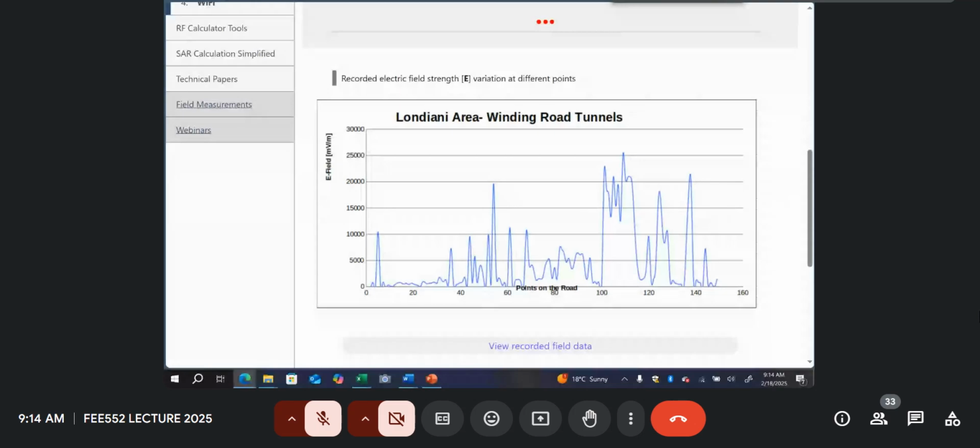So when you are planning your link in a hilly area, you may be seeing the hill that is going to receive that transmission link. But in between, there's also a hill where people live. It means that middle hill would actually experience very high levels because the transmission link now is a very high power link. So it's not what we call the air interface between your phone and the BTS.